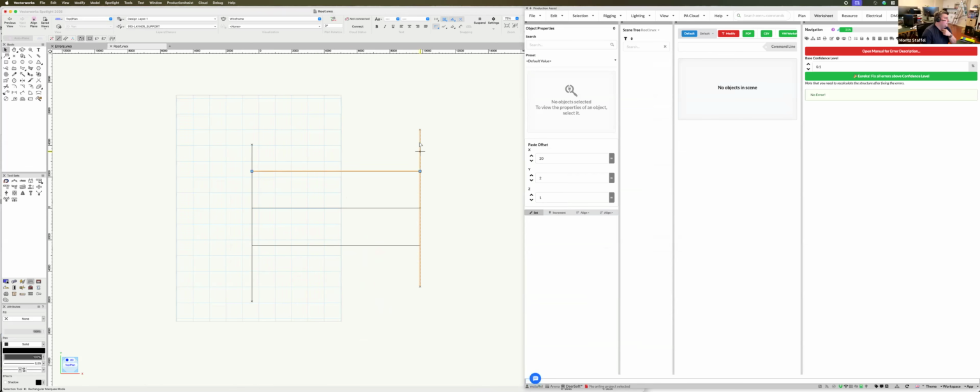So for example, there's one main beam and there are several spreader beams in here. And they do have different load capacity based on the load that is applied to the beam. In Production Assist, we now have a feature to actually allow you to calculate the specific things in here and define for a specific beam a maximum resistance in here.